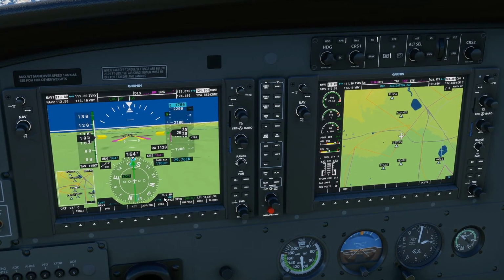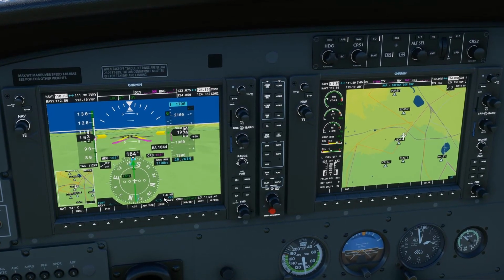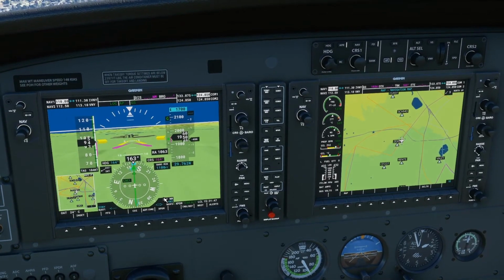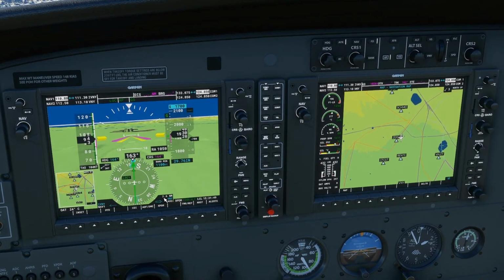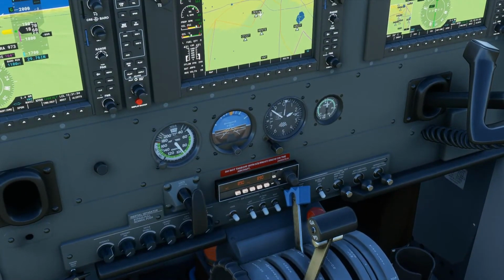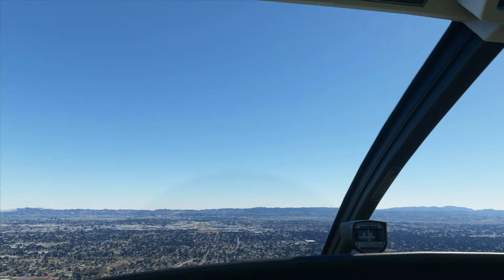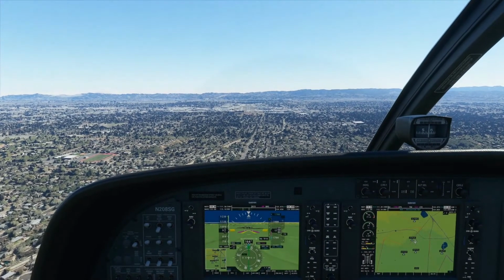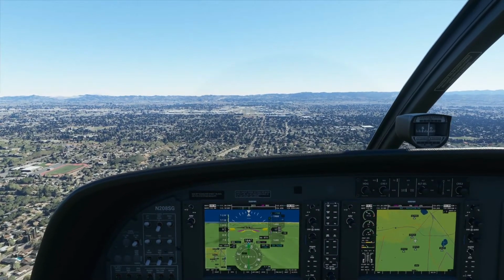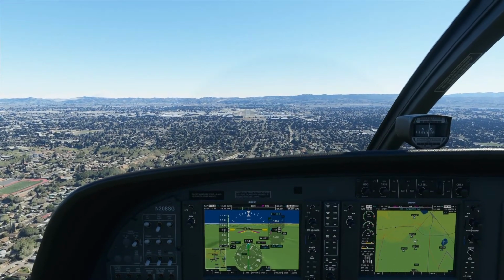So there it is, 2,000 feet. I'm gonna set flap 30. Okay, and set our props before we go around. Set our power, flaps are 30, props are good. 2 mile final runway 16 right. That is good. We are all set here. Good. And we have the runway in sight already.